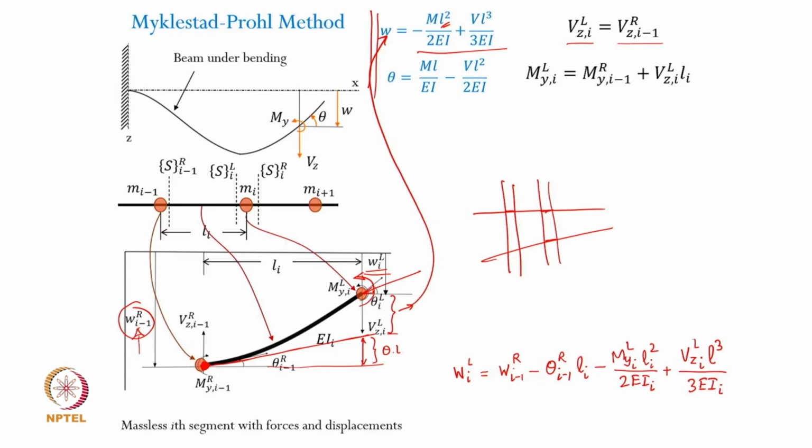In fact theoretically you can also have different material. So if you have functionally graded materials, if you have material properties which are changing with the spatial coordinate, then you can in fact theoretically have different E value as well. But this EI can pertain to the flexural rigidity in the ith segment, okay. So you can have subscript i representing that particular segment's property.